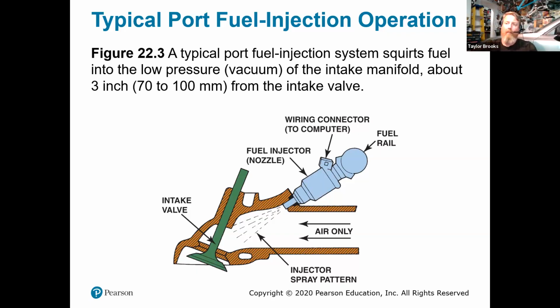When the piston drops down on the intake stroke, it draws intake gases, the intake air and gasoline, through that port. Some of the gas that did not get sprayed or was left over from the fuel injector on the prior intake stroke can get mixed with that. So we can have some fuel deposits coating the intake manifold.